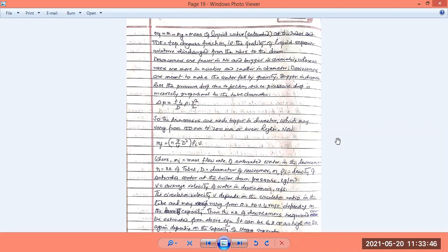And we know that we have a circulation ratio. What is the flow rate of the circulating saturated water down the downcomer, and what is the flow rate of steam released from the drum? So how much liquid water is coming down, and how much steam is going out of the drum to the superheater? In both cases we are calculating the ratio of the fluid coming out of the drum, one is water, one is vapor. The circulation ratio is the flow rate of circulated water in the downcomer divided by the flow rate of steam released from the drum itself.